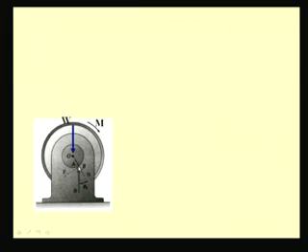So, the moment or the couple of these two equal forces, that is W and R, has to be balanced by the applied moment, else this couple, which is anti-clockwise, will retard the motion. That means the wheel, which is revolving or rotating, will come to a stop if this M is not applied.